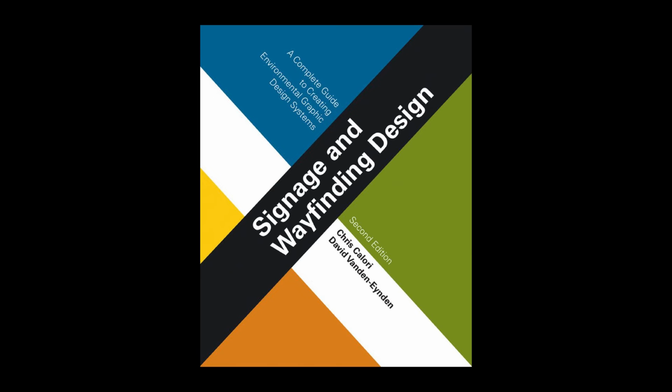Masonry. Masonry is a somewhat uncommon material for signage, but thanks to its inherent monumentality, it can be used to great effect. Masonry materials for signage include stone, brick, and precast concrete varieties that are typically used in architectural applications. Masonry can be used for sign faces and plaques, and masonry signs can be either solid and self-supporting or supported by an internal steel structure.